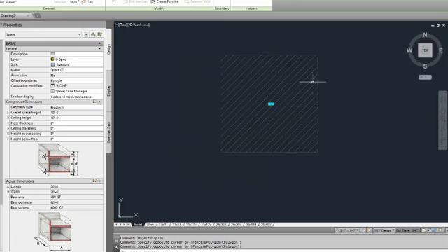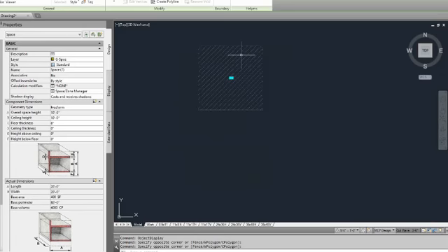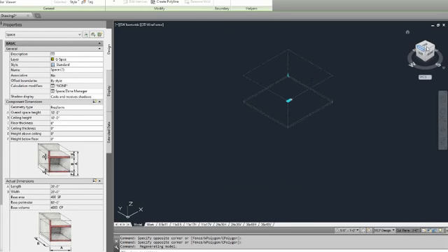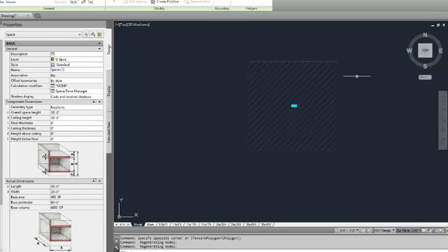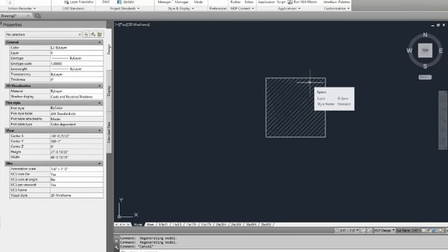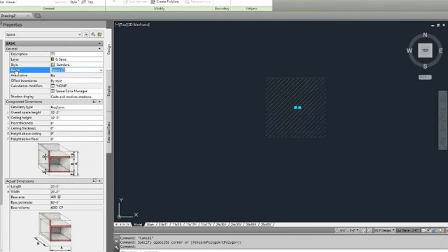Yes. Yes and yes. You can use this for access space. I believe if you talk to Steven, he probably has a better solution for you. But this is certainly usable as access space. And because it is an AEC object, and your VAV boxes, if you've created them as multi-view parts, are AEC objects, you can also anchor this to your VAV box so that it will move and rotate with your box. As far as tags go, yes, you can create tags for this.